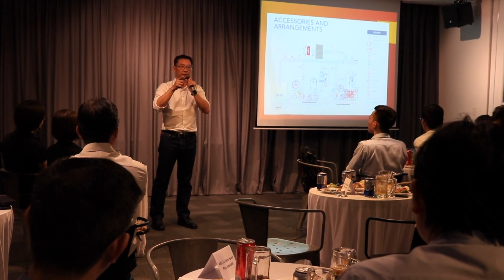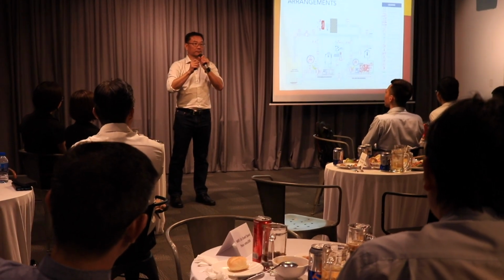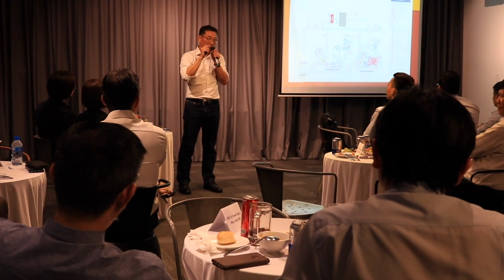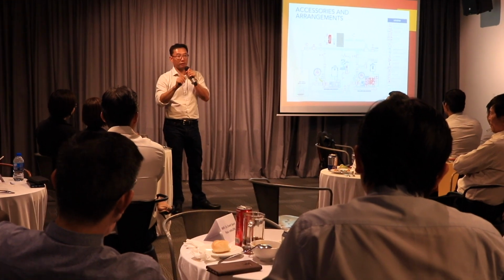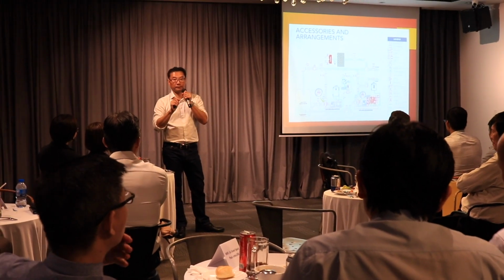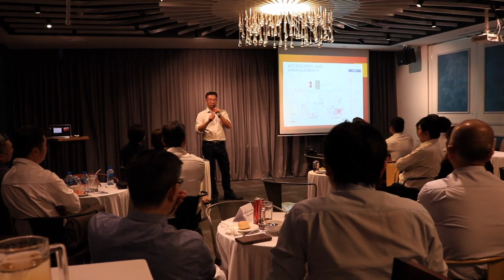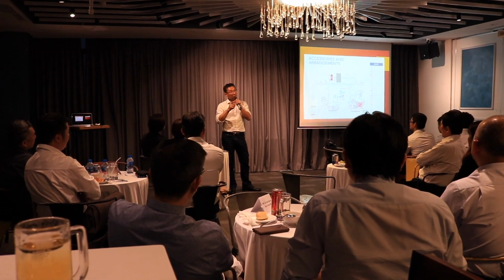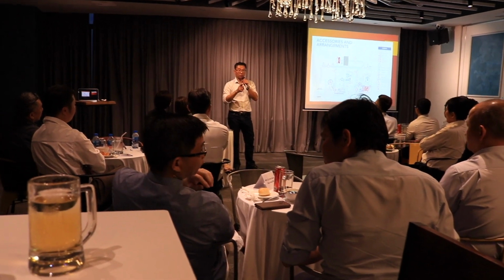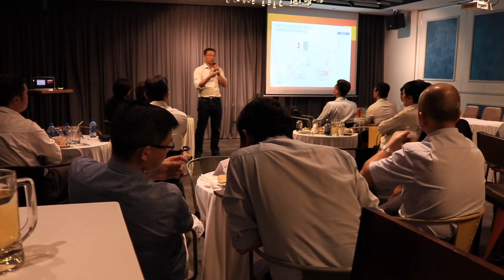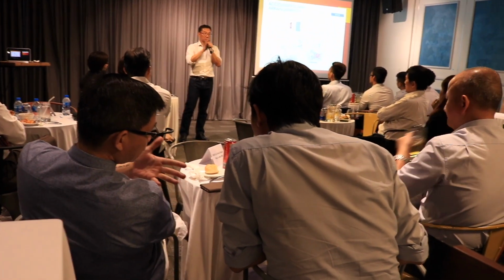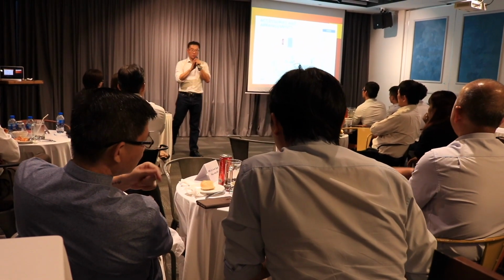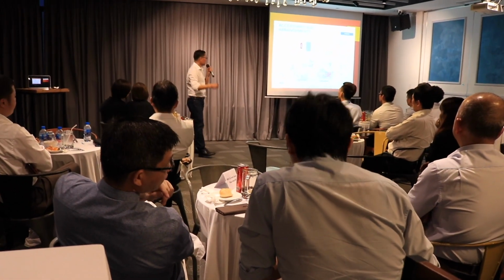Cancer is proven. So if you ask for a fire pump from your supplier, please make sure they give you Teflon or pure graphite packing. Do not use asbestos, because it may not harm you, you may not know now. 10 years down the road, you'll be queuing in the hospital. I guarantee you. And it's true, I'm not just frightening you. Okay, because it's packing, so please be sure of this.